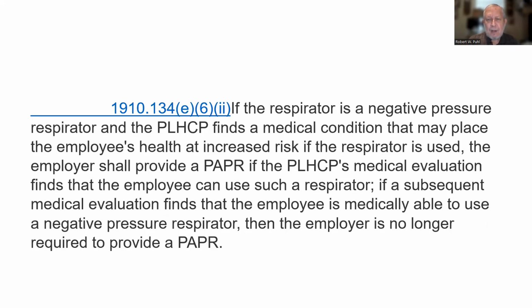So if the respirator is a negative pressure respirator and the PLHCP finds a medical condition that may place the employee's health at increased risk if the respirator is used, the employer shall provide a PAPR if the PLHCP medical evaluation finds that the employee can use such a respirator. If a subsequent medical evaluation finds that the employee is medically able to use a negative pressure respirator, then the employer is no longer required to provide a PAPR.